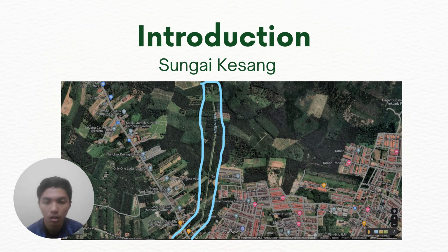To avoid the soil deformation problem at a site, an engineer will employ several solutions to resolve the problem. One such solution is micropiles, in which a small cylinder will be dug down under the soil which has the soil deformation problem. After it is dug down, the cylinder will be filled with concrete or other materials to make the pile stronger. The piles will act as a composite in the soil, which will strengthen the soil integrity.